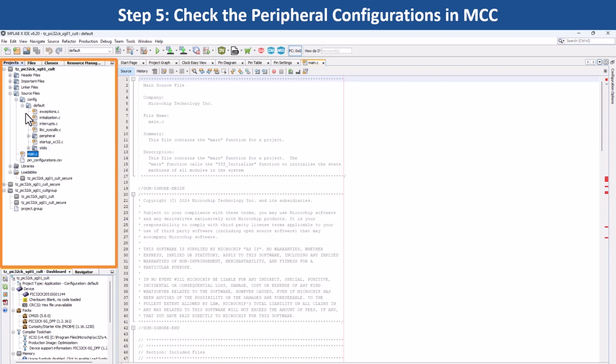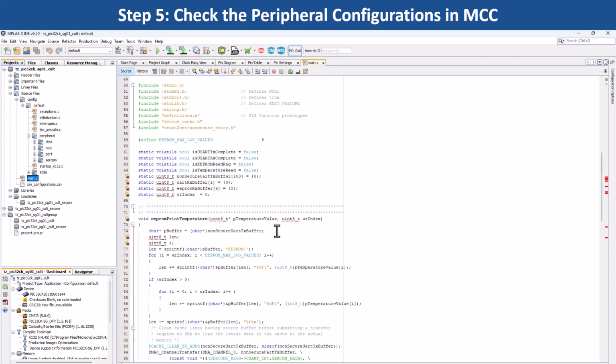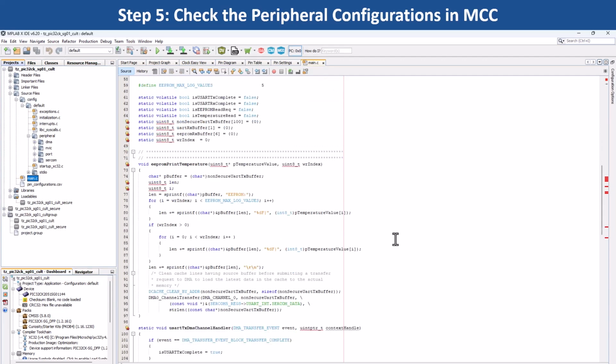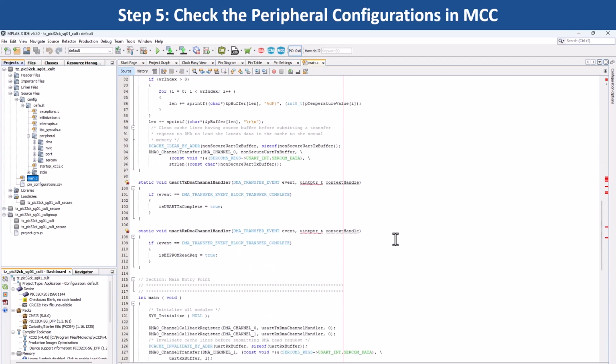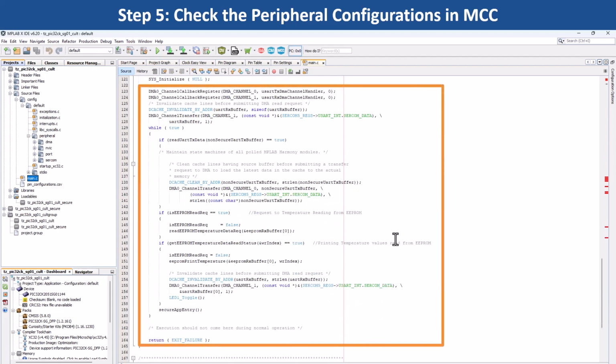The basic application demonstrates an LED toggle on a timeout basis and prints the LED toggling rate on the serial terminal. This code uses the UART to periodically send the strings. The periodic timeout can be changed by pressing switch SW0. The extended application prints the current room temperature periodically using the IO1 Xplained Pro Extension Kit.